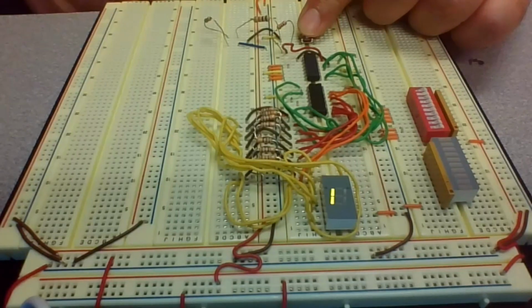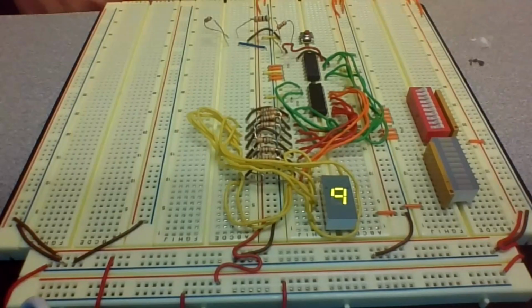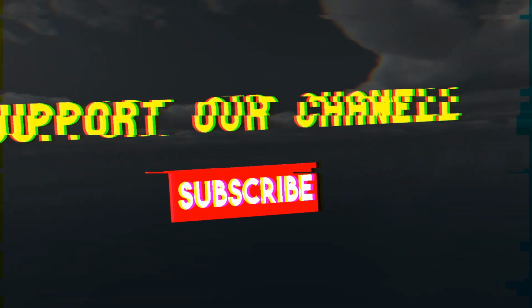So I'm doing that again, just trying our chance to see if we could count and see all those numbers. Start with the 3, 4, 5, 6, 7, 8, 9, 0, 1, 2, 3, 4. So as you could see, it works. So this shows how you could use the BCD counter and show the result on the 7 segment display.